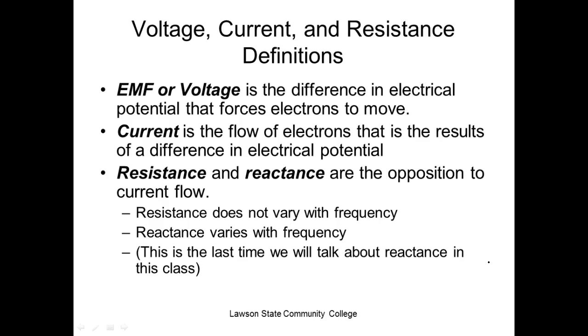Plus noise that gets into your system. So you got your spark plugs out there firing, generating noise all over the place. So what we'd like to do is not let your radio pick that up anymore. So the radios do what? They filter it out. Also, they create what we call phase shifts, which allows single phase motors to rotate. You literally got to deliberately shift something. And I'll try to show you that too. These are reactance devices.